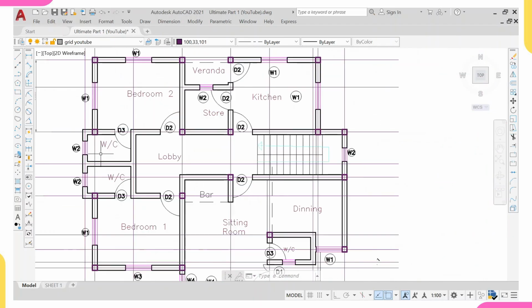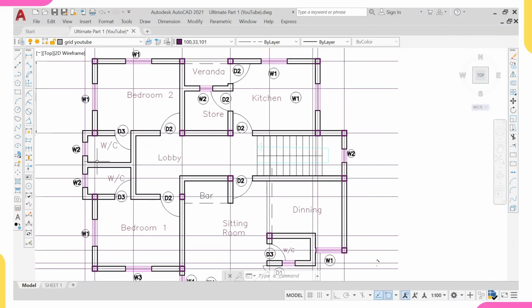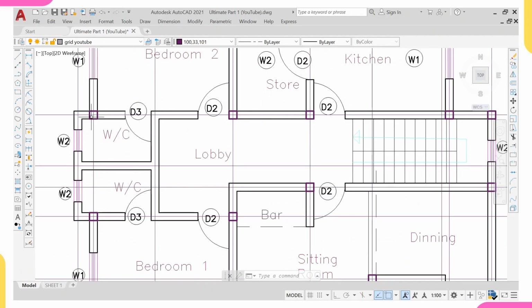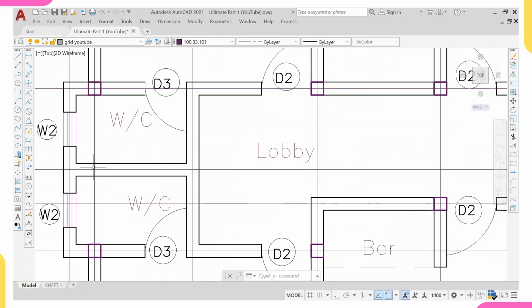Another thing in column placement is that as a structural engineer, there are two things that are necessary to us, which are, one, safety. Safety is our priority. But then after safety is to save cost. If you check most buildings by people that don't really have the knowledge of structural design, they might just come here and place a column here because they are seeing a block wall here. If you are placing a column here, you are not being economical in your design, because these two columns will be able to carry the load coming from this slab.